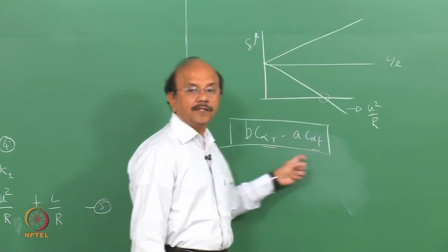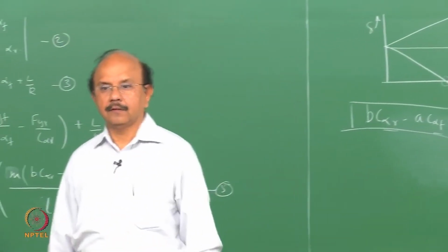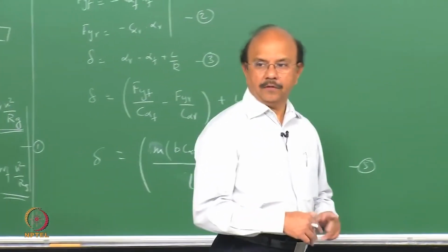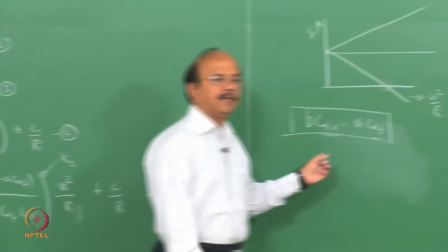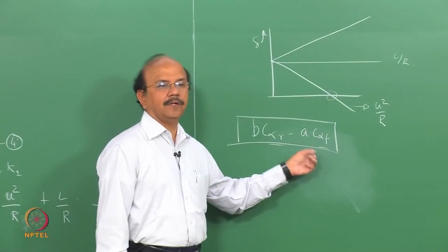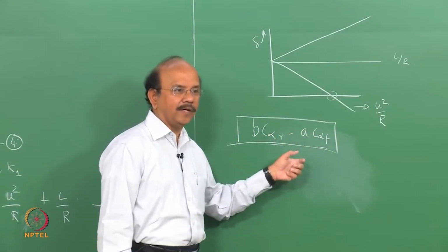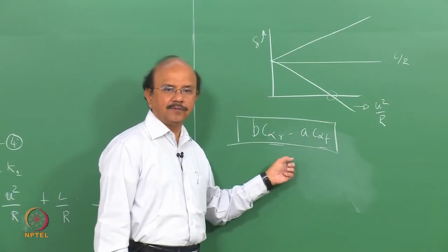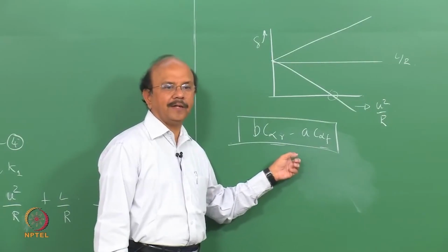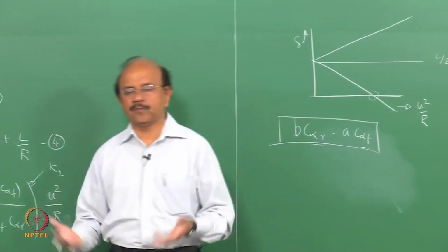So mixing this is going to have an effect because of that factor. That can be a huge factor when it comes to the mixing. Okay. Fortunately, they have a radial at the rear and a bias at the front, so the factor actually increases, so it's not a problem. But if it's the other way, then you will get into trouble. So it's better that when you mix them, you are aware that it will affect the handling characteristics. Of course, in cars, no one uses bias tires, so it doesn't matter.